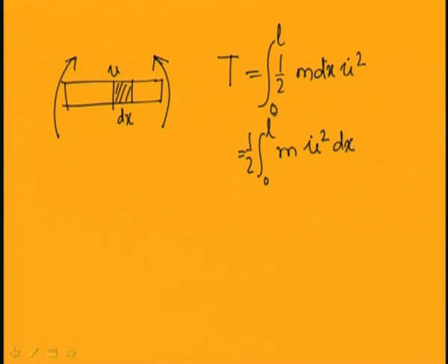Now, to derive the potential energy, the potential energy is the same as the strain energy. So, I can derive the strain energy similar to the previous case. This is equal to half stress into strain into dV, where dV is the elemental volume I have considered, sigma is the stress and epsilon is the strain of that element.